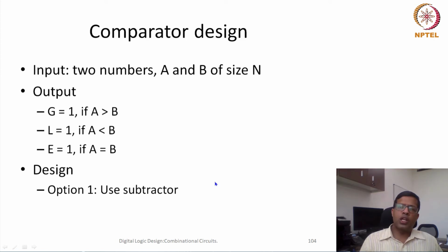If in the circuit where we are using the comparator there is already an adder that could be reused, then people use this type of comparator. Because we are able to share that adder and reutilize it for other purposes, we use this comparator. For example, in a computer system or a processor, only one of addition, subtraction or comparison would take place at a time. In that case, it is very common that we use this type of comparator.